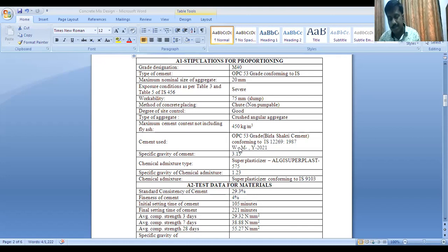Always take a sample of the cement and scrub it with your hands. If you find it very smooth and have a cool feeling, it is okay. You can throw the cement on water, and it will float for some time. It will not directly dip down in the water. It will float for a few seconds. That gives you some quality assurance about that cement. You must have the smooth, cool feeling. There are no clinkers, no lumps in a given cement.